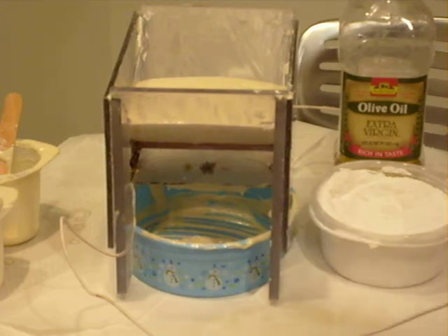Now we're going to take the power back down, and you should see that it starts flowing again. As we watch it flow, we're also going to talk about some of the limitations of an electrorheological fluid. MR fluids and ER fluids share some similar design limitations, one of which is sedimentation of the fluid. We actually saw this in the construction of our demo. We mixed together our ER fluid early last week and then left it sitting around, and found out that it was completely useless when we came back to it 5 or 6 days later.